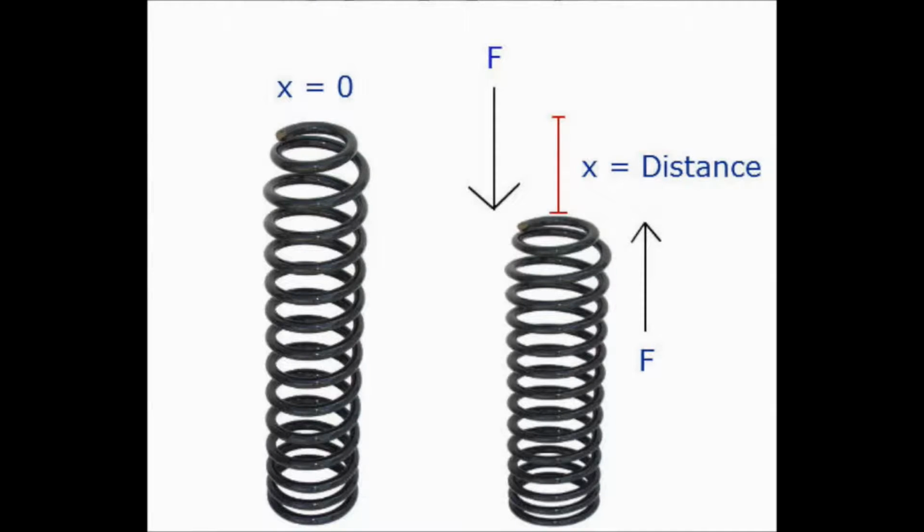Spring rate is the criteria used to describe springs by measuring the constant amount of force it takes to extend or compress a spring a certain distance. For example, if a force of 10,000 newtons is applied to a spring and it vertically compresses 1,000 millimeters, the spring rate would be 1,000 newtons per millimeter, force over distance. This graphical representation of the spring rates shows the top line is a much stiffer spring, while the lower line has a much softer spring rate.